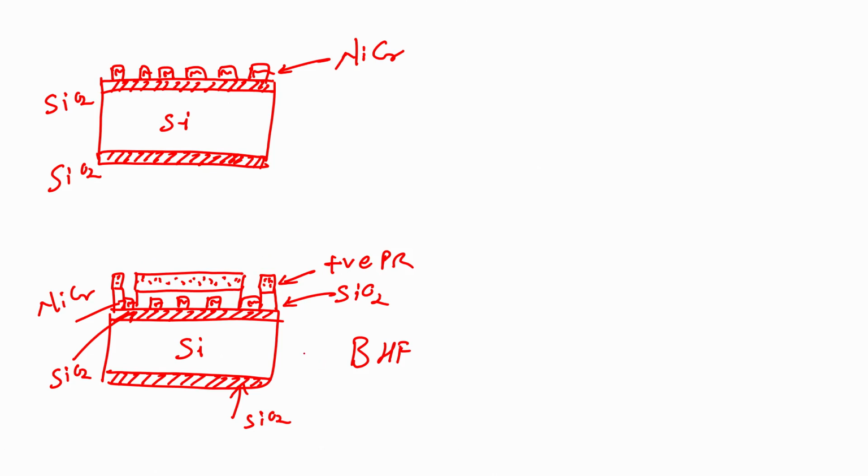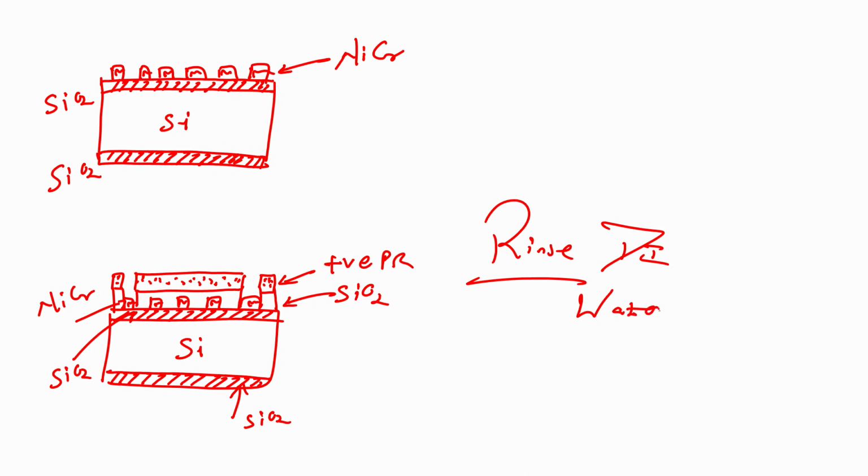After BHF, I rinse it. In every step, understand that there is a rinsing. You have to wash the wafer with DI water. Rinse the wafer with DI water. After every step you have to go for rinsing with DI water.